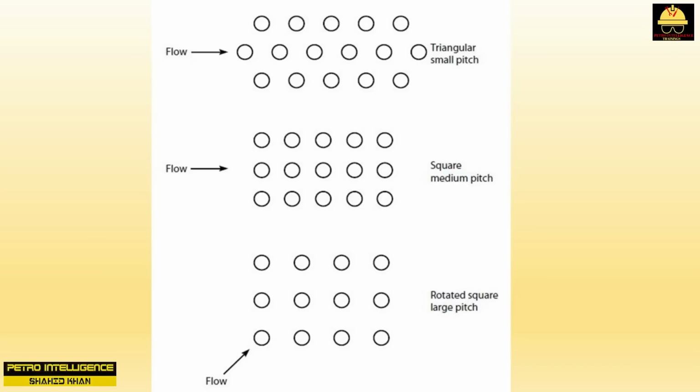Once the space between adjacent tubes is bridged over with deposits, the flow of fluid between these tubes drops to zero. The local heat transfer rate drops close to zero. Overall, shell side delta P rises as flow is diverted away from the restricted zone. Using the larger tube pitch will reduce the number of tubes in a shell by about 35%. But in a fouling service, this may greatly increase run times between cleaning and, in my experience, is a worthwhile incremental investment.